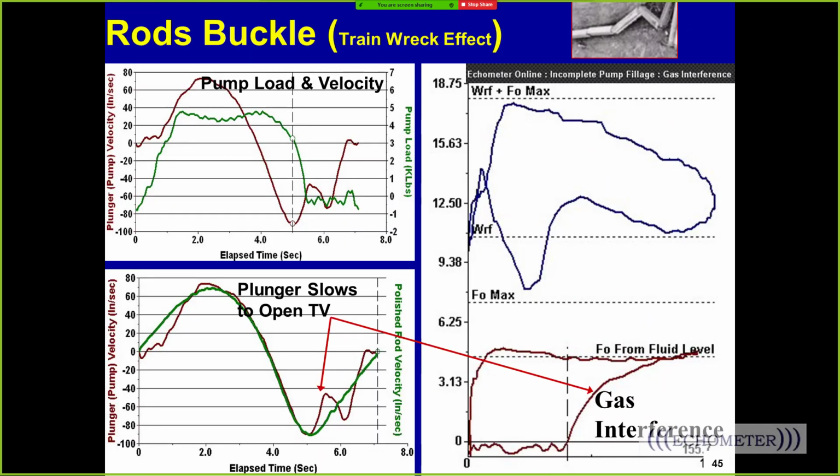Not really, but with the polished rod transducer, the way that the zero load line is determined is based on the plunger velocity, when the pump is moving.